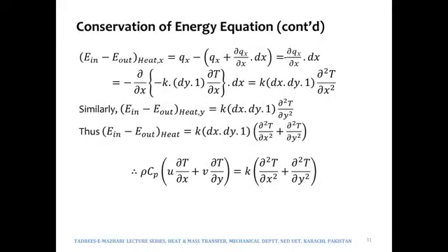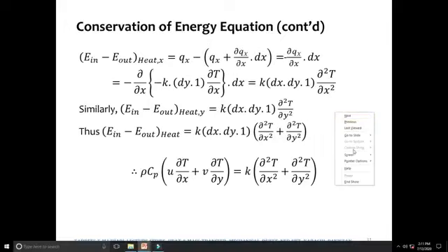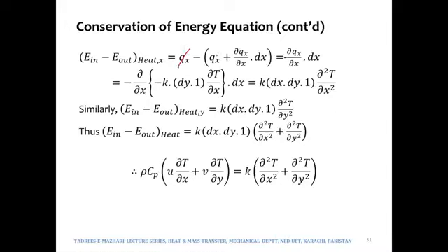We would not be considering the delta E due to the work, for the obvious reason that we are considering heat and mass transfer only. So due to heat, it would again be Qx minus Qx plus ∂Qx/∂x times dx, and over here we know that this Qx and this Qx will get cancelled out, so it would be minus ∂Qx/∂x times dx. And again it is ∂/∂x of Qx, so Qx can be written as minus kA ∂T/∂x, and dx is written as it appears.